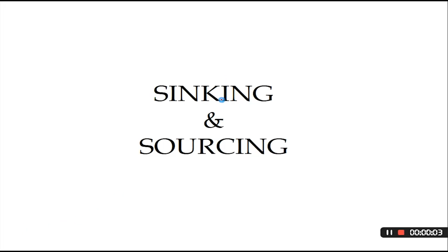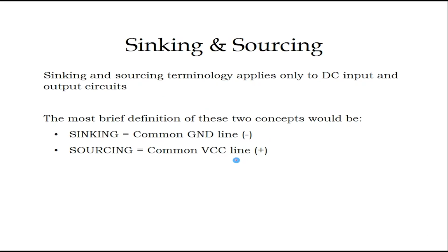In this session, let's understand the concept of sinking and sourcing. It is very important to understand the sinking and sourcing concepts in PLC wiring to make the right decision on I/O connection. Sinking and sourcing terminologies apply only to DC input and output circuits, not AC, because of the polarity. By definition, sinking means a common ground line and sourcing means a common VCC line or a power line.